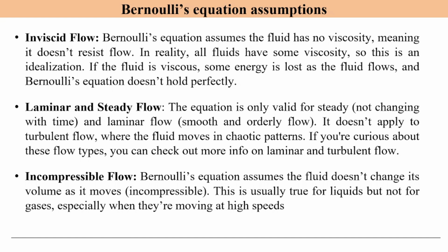Steady flow means the velocity at a given point doesn't change over time, while laminar flow is smooth and orderly. If the flow becomes turbulent, moving in a chaotic pattern, Bernoulli's principle no longer holds. So it doesn't apply to turbulent flow, where the fluid moves in a chaotic pattern. Now the third condition, incompressible flow. Bernoulli's equation assumes that the fluid doesn't change its volume as it moves. This is usually true for liquids but not for gases, especially when they are moving at high speed.